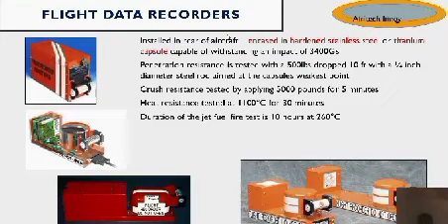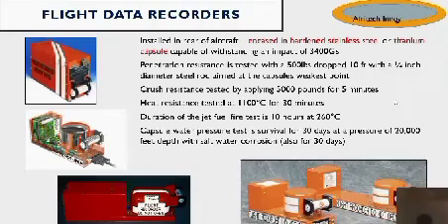The jet fuel fire test lasts 10 hours at 260 degrees Celsius. The capsule water pressure test is survival for 30 days at a pressure of 20,000 feet depth with salt water corrosion. So these are all the tests that they do on this flight data recorder, and if it passes them, then it is fit.